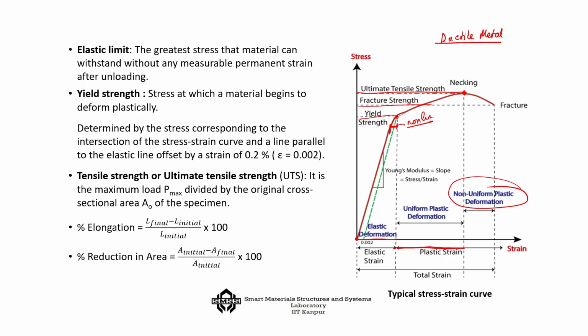So, you see that in this stress strain diagram you get so many pieces of information, right. You get first of all this ratio in the linear domain, and that will give you the modulus of elasticity. So, the slope, you are going to get the modulus of elasticity, and then you are going to get the strength information, the yield strength, okay, beyond which the plastic deformation is setting in. Okay. So, that is the yield strength point, and then you are going to get the fracture strength in some cases, but for ductile material you are going to get the ultimate tensile strength.